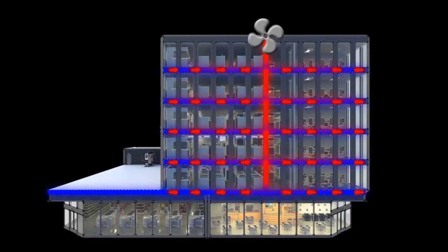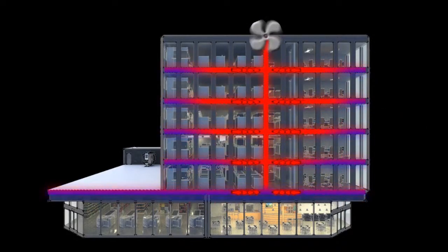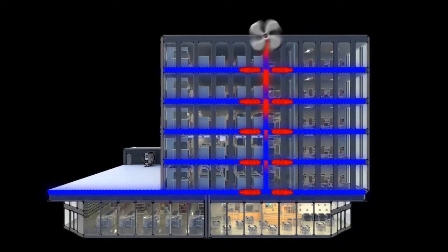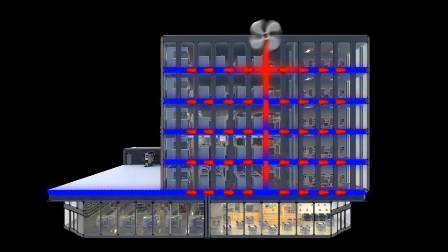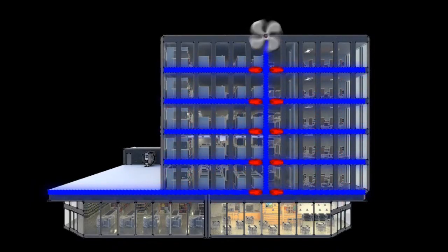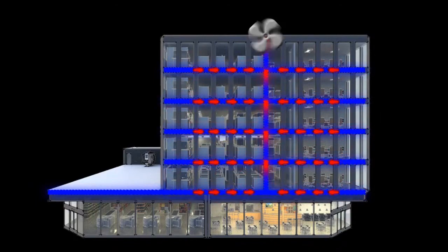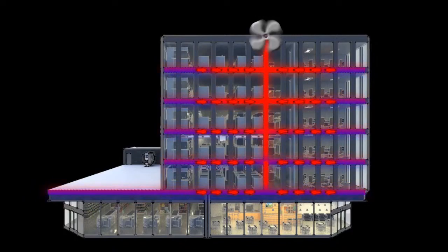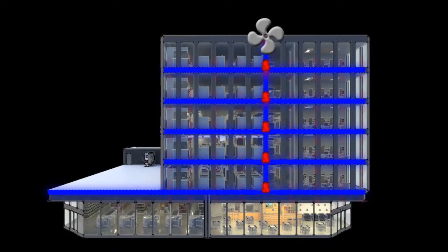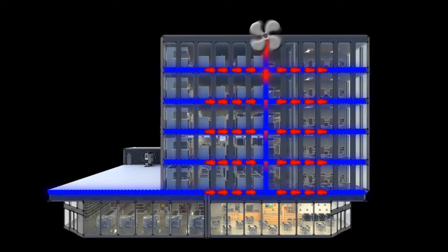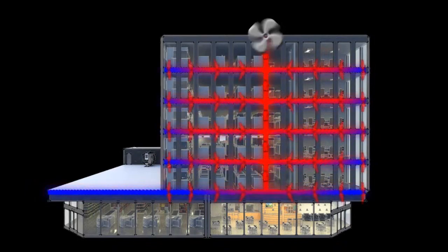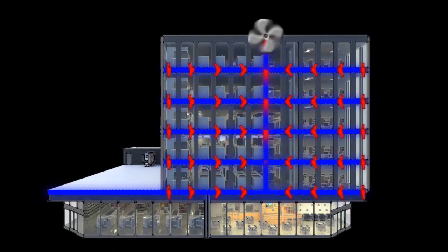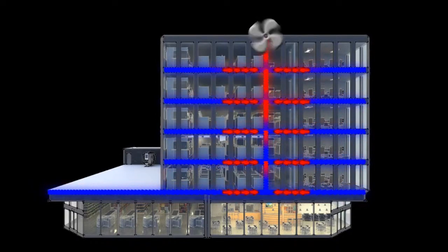In high-rise residential and commercial structures, large-scale air handling equipment is capable of creating substantial pressure drops within the building. Natural sources produce pressures of up to 10 pascals, while mechanical systems can go as high as 60 pascals. If this is not managed correctly, it can contribute by drawing air into the building envelope from unintended sources. Additionally, if the system is not installed well, leaking ductwork may draw air into the system that has not been accounted for, with a corresponding detrimental effect on the efficiency of both the system and the building as a whole.